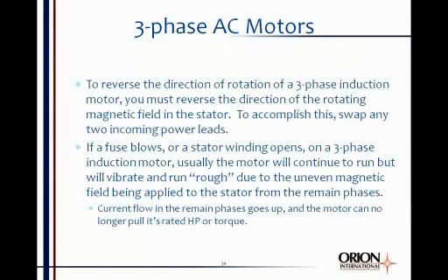Now, to reverse the direction of rotation of a three-phase induction motor, all you have to do is reverse the direction of the rotating magnetic field. If the rotating magnetic field goes in the opposite direction, the motor will turn in the opposite direction. So, in order to make the rotating magnetic field go in the opposite direction, you just have to swap any 2 incoming power leads.